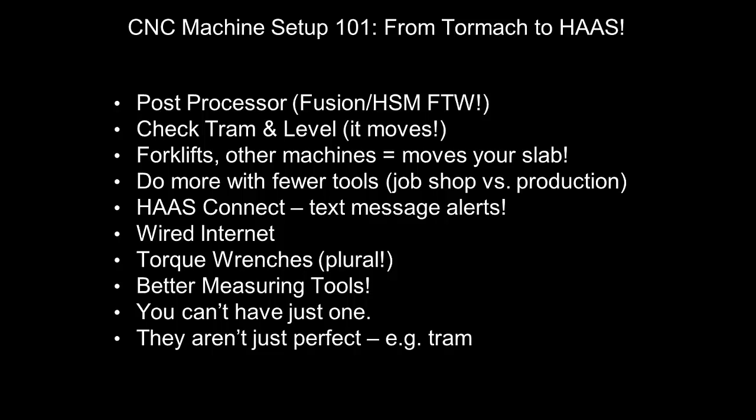I've been trying to do more with fewer tools. I find that it's harder for me as a small shop to afford and organize lots of custom tools. So for instance, I've moved away from lots of different drill sizes, and I've got 2 different really high-end through spindle coolant drills. I tend to poke holes through with those drills and then interpolate, usually with the bore operation or maybe an adaptive, to blow out that hole to the diameter I want. It saves me having to add more tools in my carousel. Obviously it takes an additional tool change, but that's the balance of what's more important.